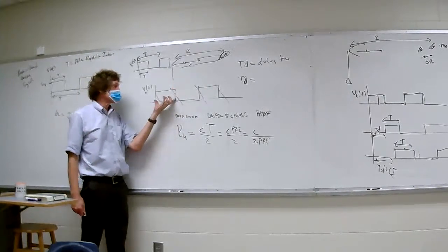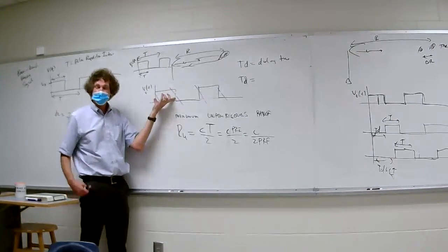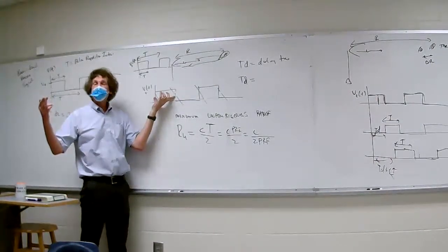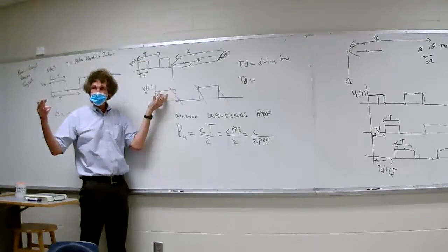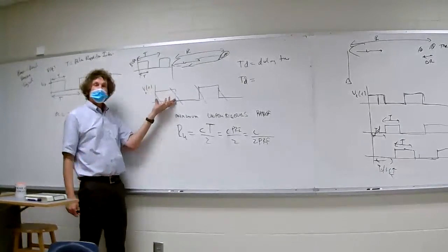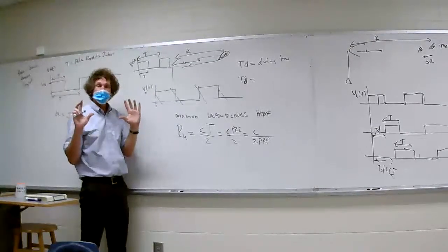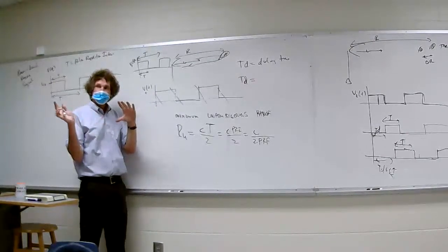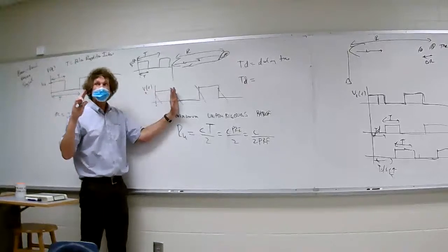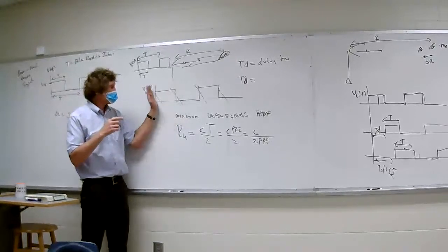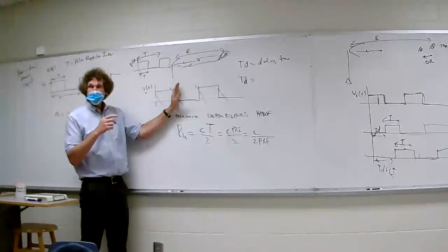This is why these duty cycles are typically tenths of a cycle. So it's only on for 10% of the time, maybe 5%. And if you're transmitting, you can't hear if it's the same antenna, right? So normally they have a transceiver switch. It transmits, and anything out there at this short range would be c tau over 2.